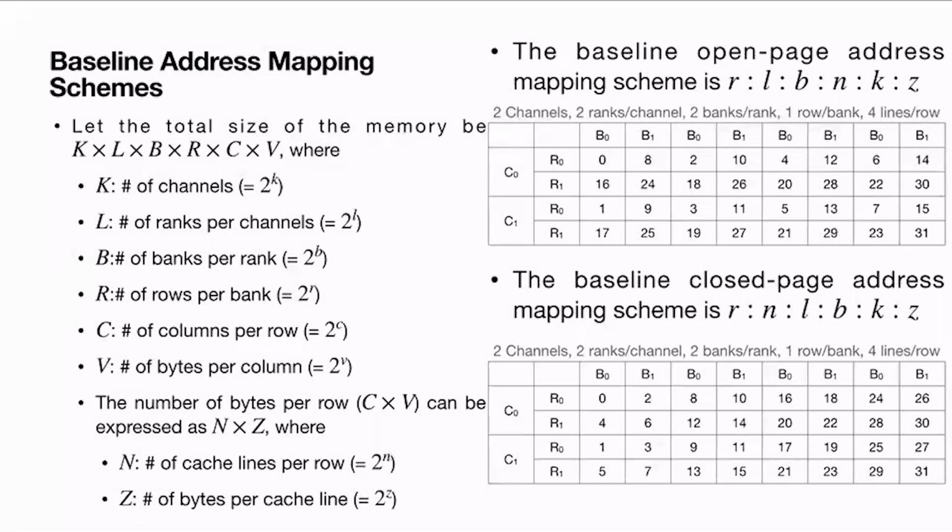And similarly, 3 also we put into bank 1 of channel 1 and rank 0. And then the next, 4, where do we put that? 4 we put into channel 0 again, but a different rank, because rank to rank switching takes less time compared to issuing a pre-charge operation. You need to see the trade-off: a pre-charge operation may take 11 or 12 cycles, whereas a rank to rank switching may take about 6 cycles. So you can save that. That's the reason why we came to rank 1 of channel 0 and put block 4 in bank 0. And similarly, the other things carry forward.